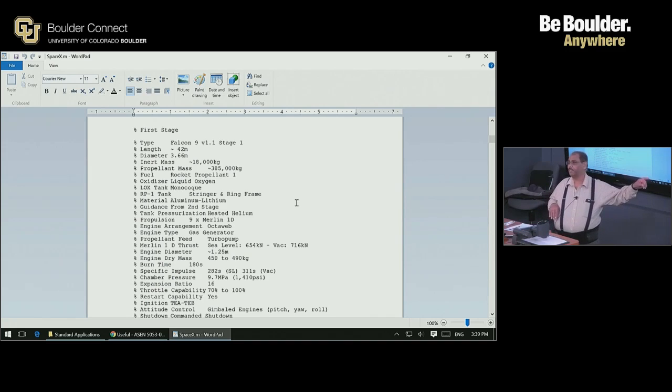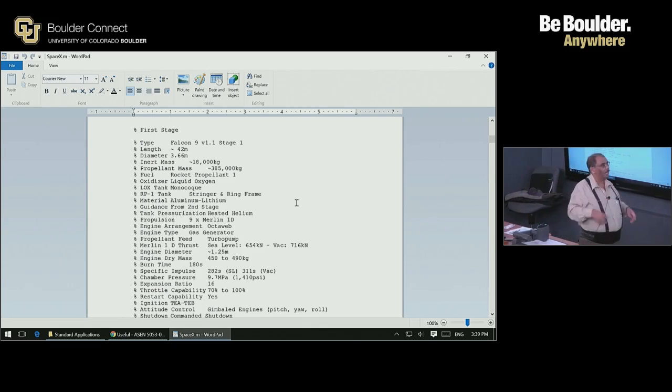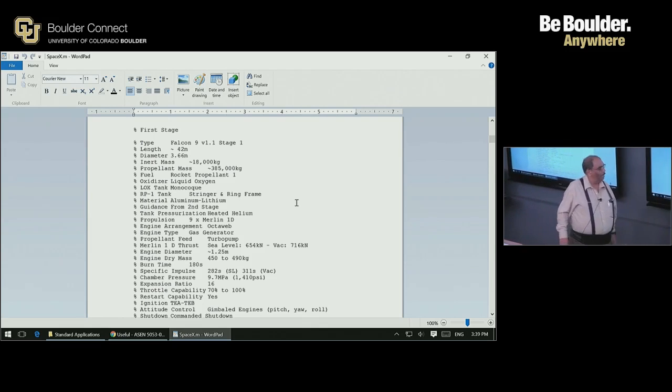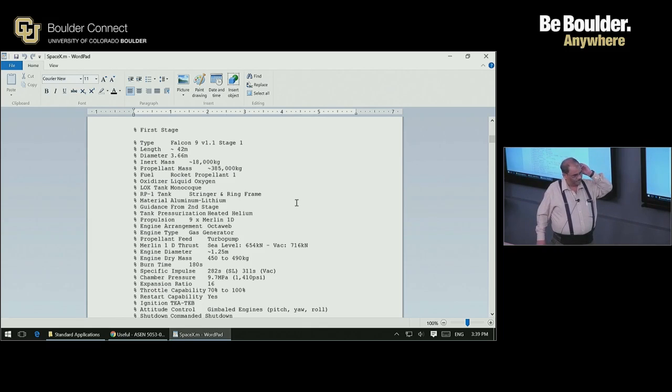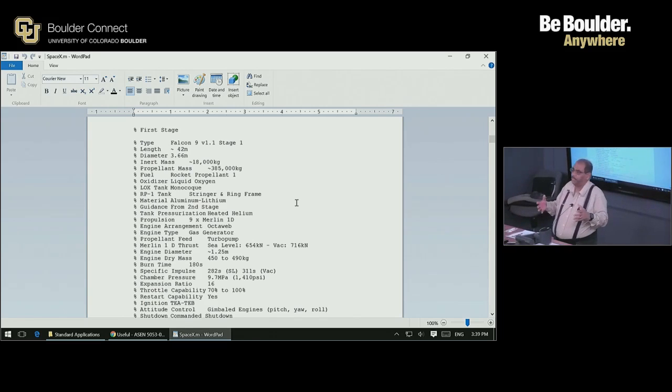Now, that specific impulse definition doesn't change if you go to Mars. Okay? G naught is still 9.81. It is just a way of making the units of specific impulse seconds, no matter which system you use, British or metric. Okay? And then the impulse is seldom quoted. It can be computed. Usually the burn time is specified. Okay, how long the engines burn. Okay, you have to design the engines for a specified burn time.